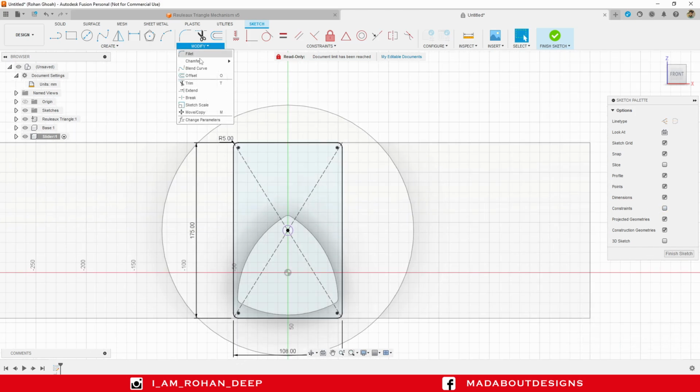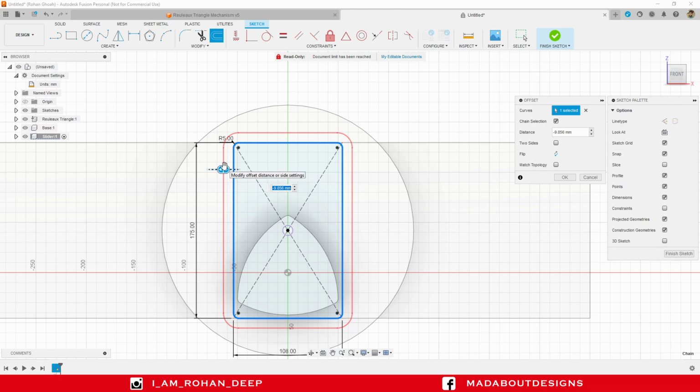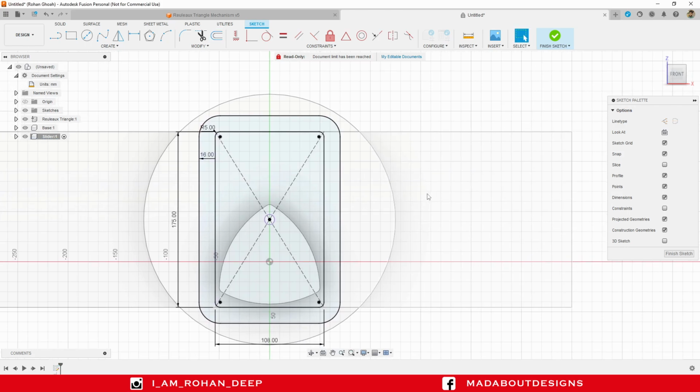Under Modify, go to Offset. Select this profile and drag it outward up to a distance of minus 16 mm. Press enter. Now go to 2-point rectangle.